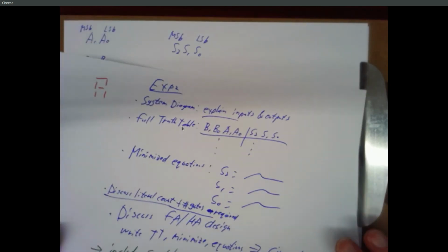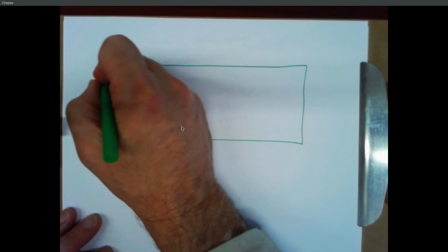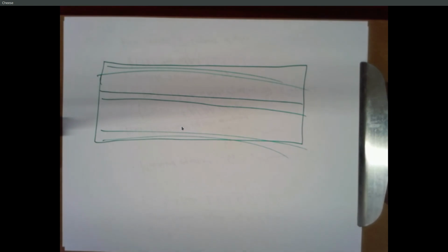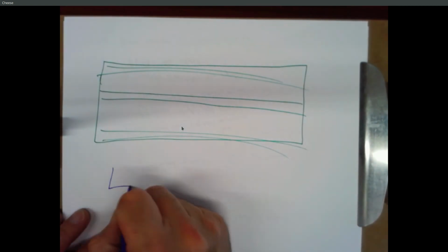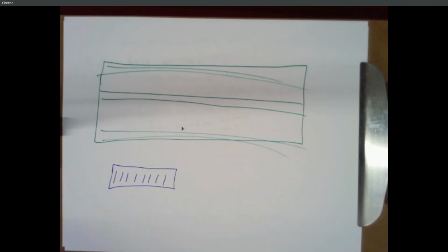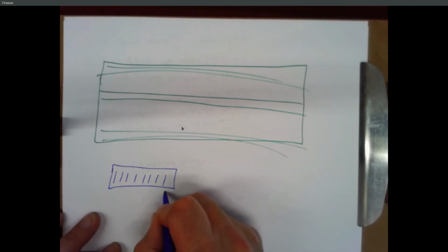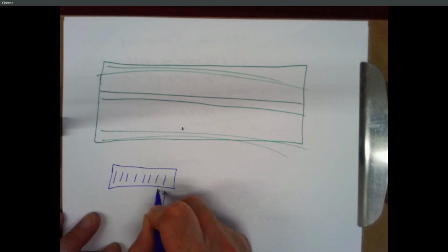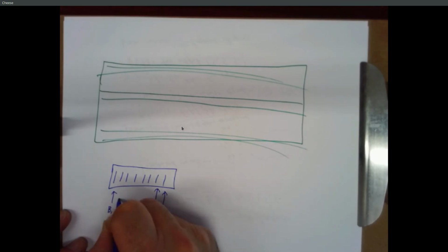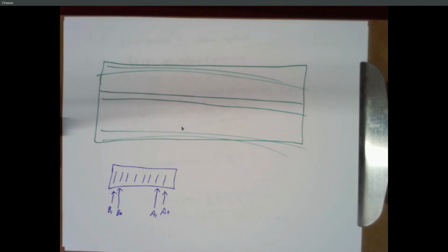All right, I'm going to put one more requirement on this. So here's your proto board. Wherever you put your switch block, I don't care where it is on the board, but I'd like you to wire your switches like this. I want this rightmost switch to represent A0, the switch next to it to represent A1. I want the leftmost switch to represent B1, and the switch next to that to represent B0. And then the 4 switches in the middle don't do anything.